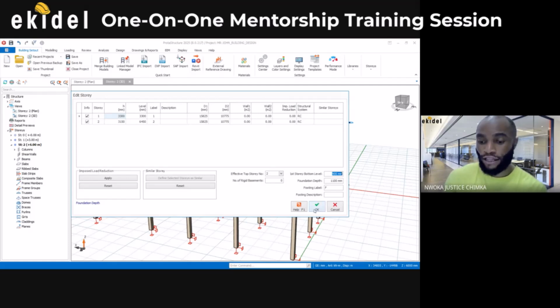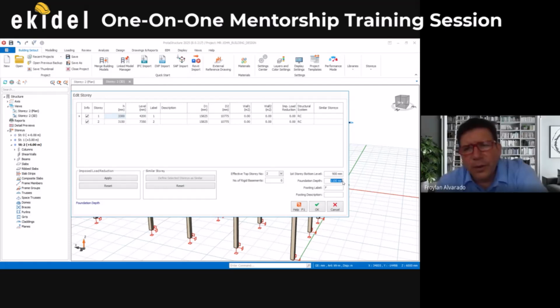So I'll come now and click on what? Once I've done this height, and then I'll apply your DPC level. Now for this foundation depth, leave it as it is, because at site it might change. You understand? Even if you add anything here, at site it might change, because they might be digging and then find clay. They will need to dig deeper or find a pit or something. So that's why we usually do the soil testing, you know.